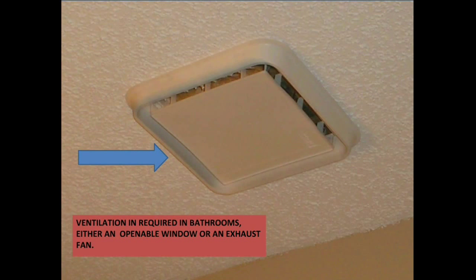Some type of ventilation is required in bathrooms, either by an openable window or an exhaust fan. Refer to the 2009 International Property Maintenance Code, Section 403.2, Bathrooms and Toilet Rooms.